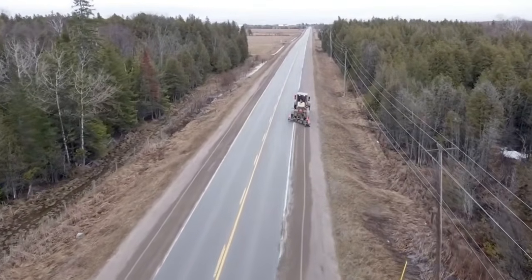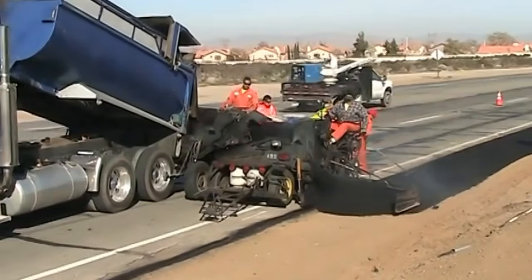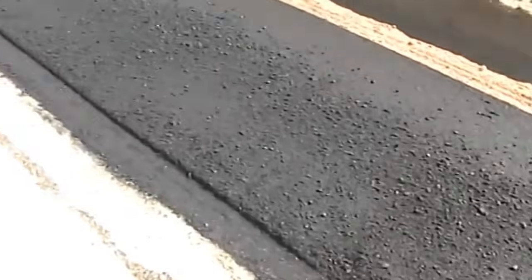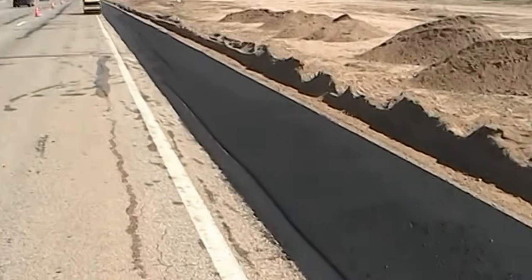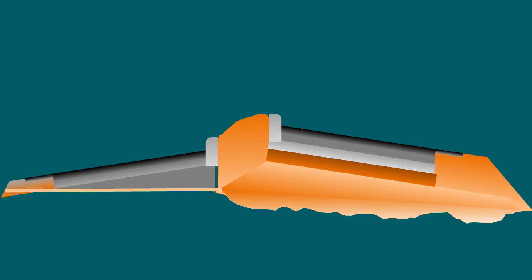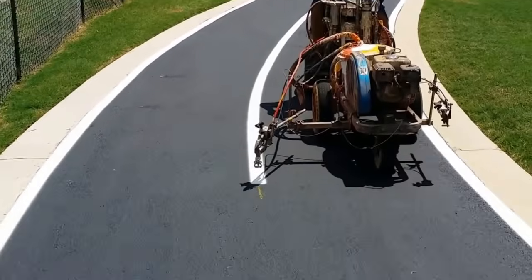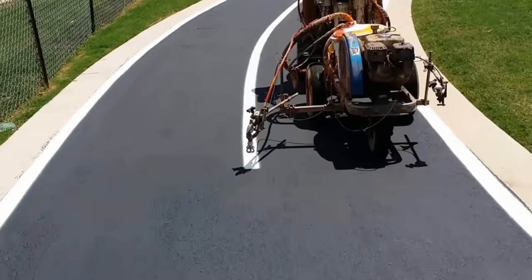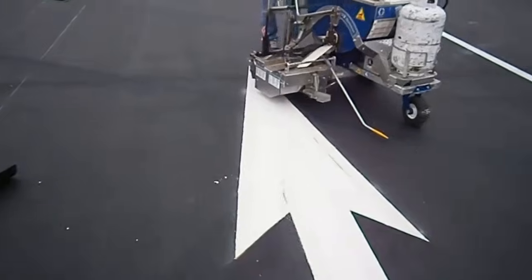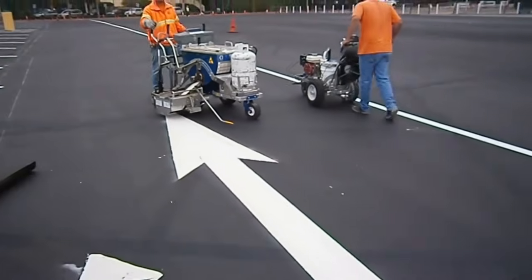A single layer of road base around 10 cm thick and a thin layer of asphaltic screed is used as topping of shoulders to seal the road base. Finally, the miscellaneous works, like central verge filling, road markings such as center line and pedestrian crossing, and the fixing of signage shall be completed before completion of the project.